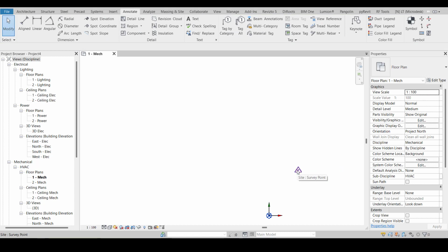Now, this is the way to get the coordinates from the existing files, or to give your coordinates to your link file. So there are two cases. Suppose you are an architect and you have multiple files received from the different parties, and all of their coordinates are 0 0. They started the project but they have not used the correct coordinate system. So in their file, what you will do, you link their file and you'll publish your coordinates to them.